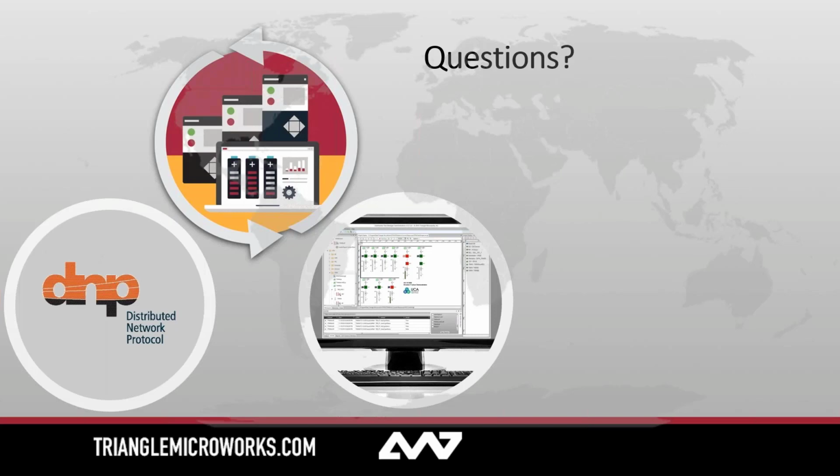Is it possible to do relay testing remotely through SCADA with DTM? Yes, it depends on where DTM is installed. You could have DTM installed on a desktop inside of a test lab, and you could absolutely remote desktop into that desktop and run DTM as if you're sitting there, and be hooked up to the switches, the IEDs, anything in your lab, and run your tests, export them, and get them back to you any way you need to.